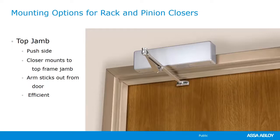You have to make sure that you have enough room on the frame to mount the door closer. We do, however, make several different drop plates and mounting plates that allow you to lower that door closer on the frame so that you have room to mount it. Where I see Top Jam closers a lot is on really heavy duty exterior doors where we need all the strength available in that Top Jam closer mount. We need more strength than we would typically get from a parallel arm. So that's where I see it.